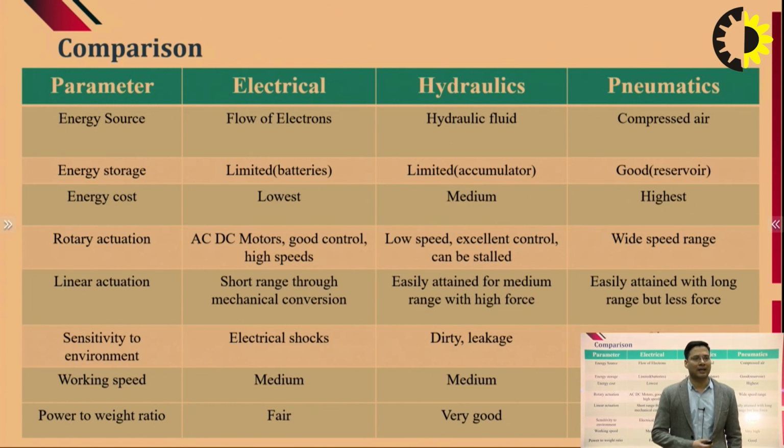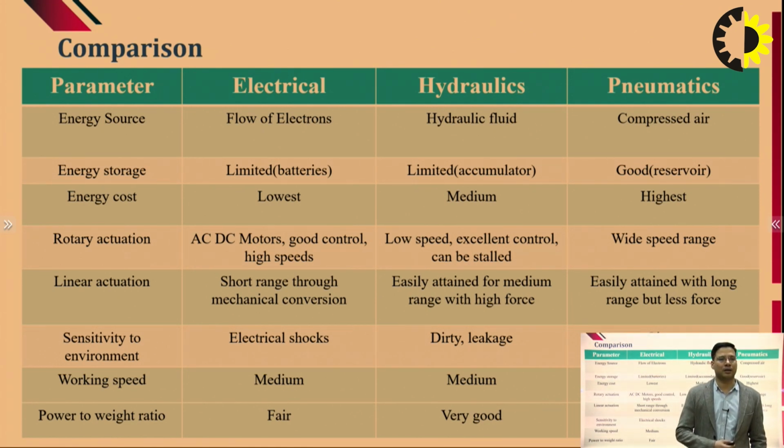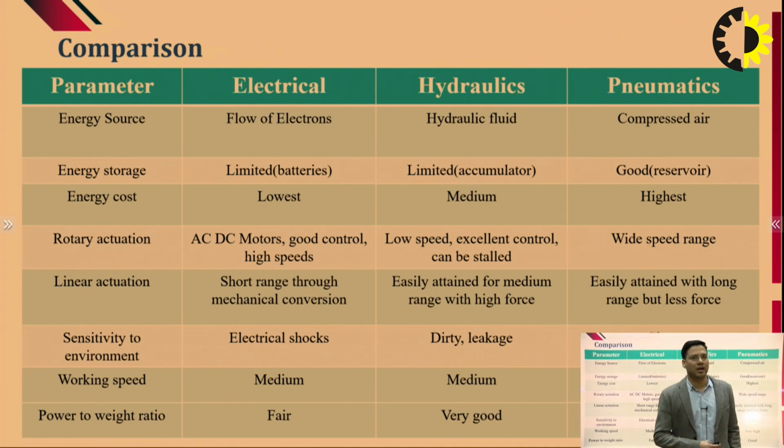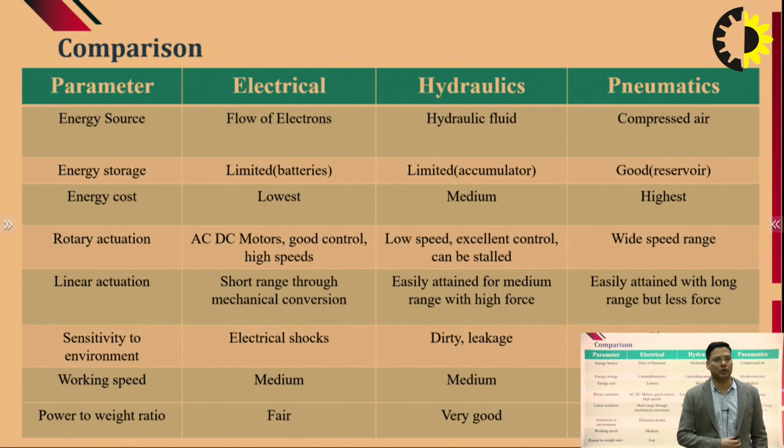Now when we talk about energy cost, in electrical we have the lowest, but in hydraulics I have a medium benefit, since I cannot store energy, so the cost incurred in generating the particular pressure or force using hydraulics is medium as compared to pneumatics. Okay, since we are in pneumatics, to maintain the desired pressure, the motor or the compressor unit has to be operated regularly.